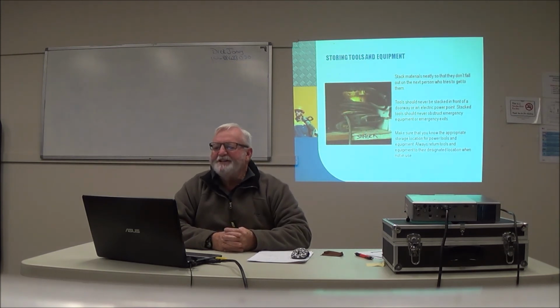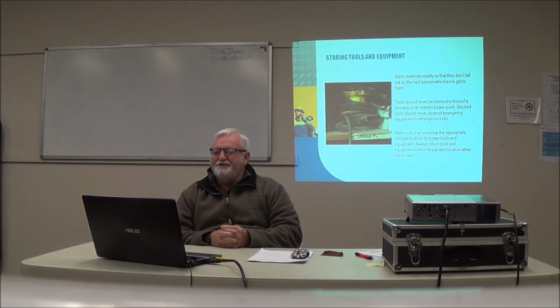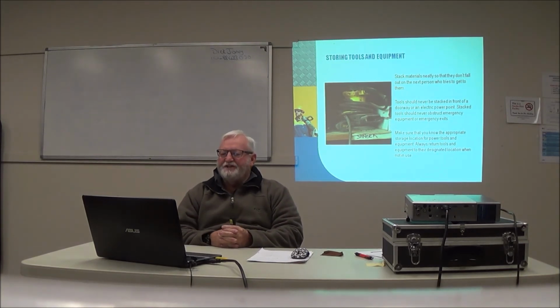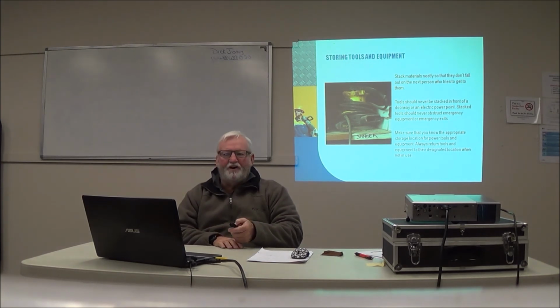Stack materials neatly so they don't fall out on the next person who tries to get them. Tools should never be stacked in front of a doorway or electrical power point. Stacked tools should never obstruct emergency equipment and/or emergency exits. Make sure that you know the appropriate storage location of power tools and equipment. Always return tools and equipment to their designated location when not in use.